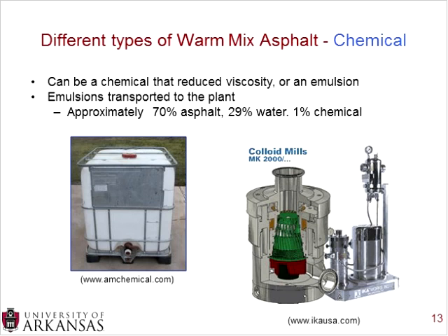And I think that technology is quite different versus the concepts that are used in a cold mix emulsion, which is where you have an emulsion off-site and you can simply take some RAP, mix it with that emulsion, and then stockpile that. And that can be stockpiled and used for a couple days, a couple weeks, depending on what kind of material you have.